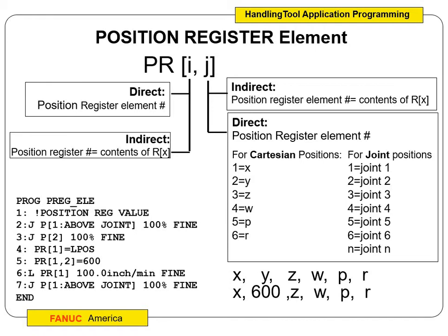So what does that mean to offset something? Well, as it goes through, say you make your box program, and say we're palletizing something. We can take your box program and say we want to raise it up 600 millimeters. That's how we would do it. We would just offset the Y 600 millimeters, and it would offset in that direction. Hopefully that makes a little bit of sense.